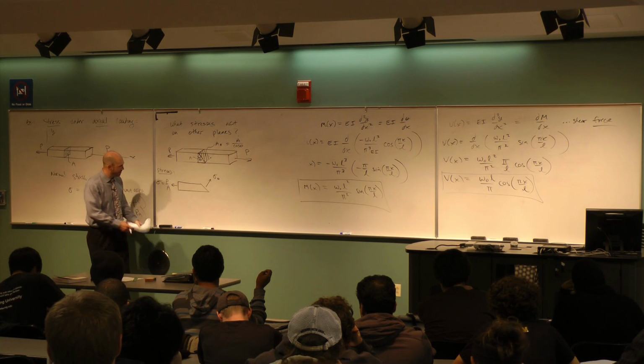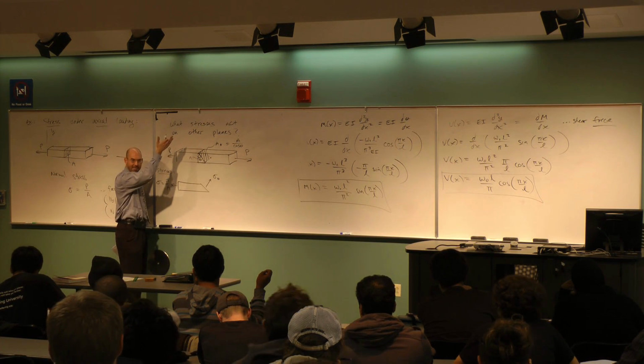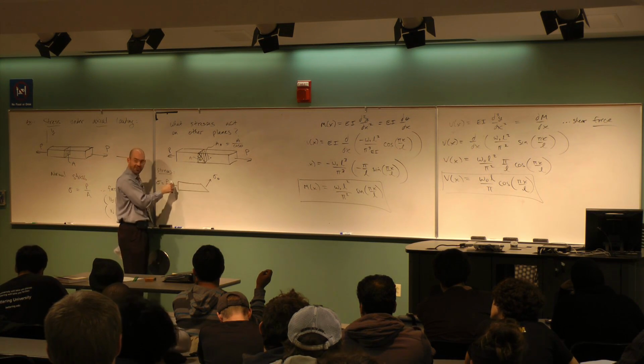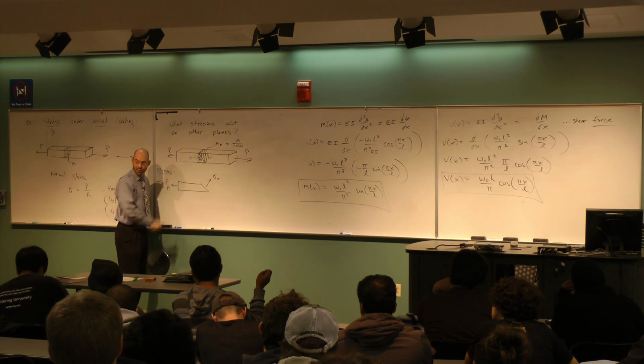Right? And how do I know that? Because it's got a net force in the y direction. So the whole thing's going to be accelerating up. And these forces aren't coincident. So I could think about force times distance, which will give me a moment, which will make it spin. Okay? It's not in equilibrium.